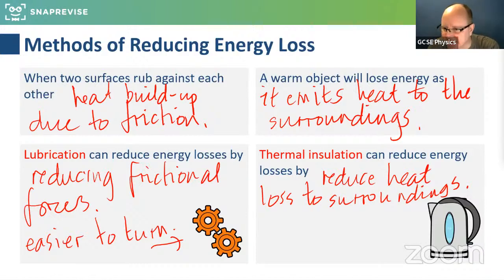Of those two points in the chat, Somalia and Thanya, I think, and Dee is correct there, I think the comments from Thanya and Dee are probably slightly better worded in the scientific sense. I do get students sometimes saying that insulation traps heat. And technically insulation isn't doing that, it's trapping air or providing a low conductivity barrier between something that's hot and something that's cold. So I try and avoid saying traps heat, but certainly you can say reduces thermal energy transfer, and it will increase the temperature difference between one side of the insulation and the other, so that's correct too.